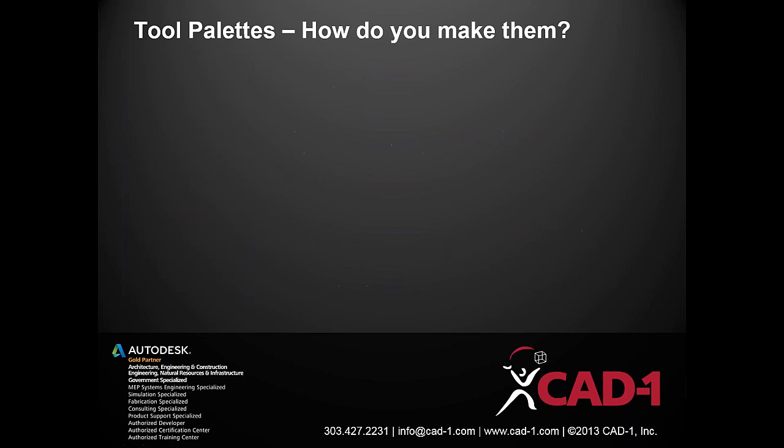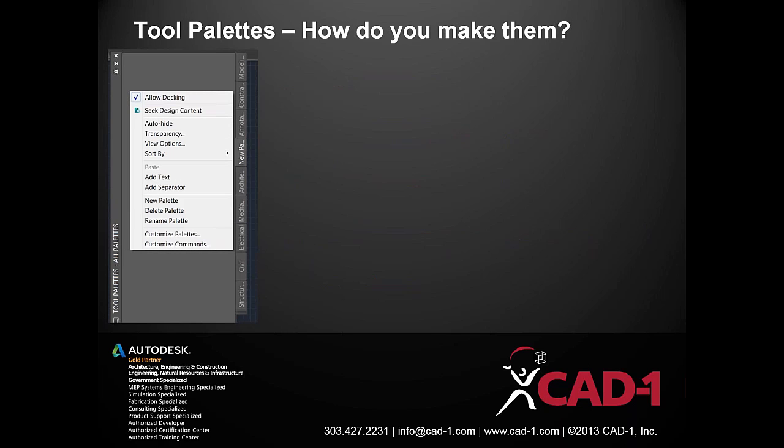Next up, you saw what they are and how to work with them. How do you make tool palettes? Well, the quickest way of making everything inside of AutoCAD is a right-click menu. When your tool palettes are up, you can right-click on top of a tool palette or right-click on the name bar of the tool palette, and you're going to get some really great options in here, such as creating a new palette, deleting an existing palette, renaming the entire palette if you want to.